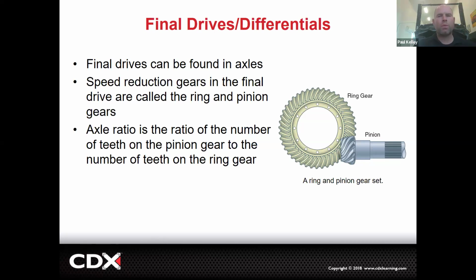Part of the reason that we want to make it easy for the technician to know what the ratio is, let's say you're working on a 4-wheel drive and you have to rebuild the rear differential. If you put the incorrect ratio in the rear and it's different than the front and they put it in 4-wheel drive, the thing's going to be nuked. Assuming it's a part-time 4-wheel drive. If it's a full-time 4-wheel drive, it's going to get nuked whether you put it in 4-wheel drive or not. And so this is the final reduction.